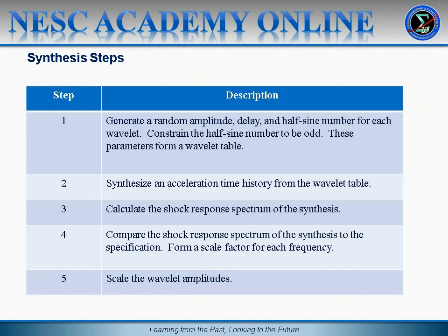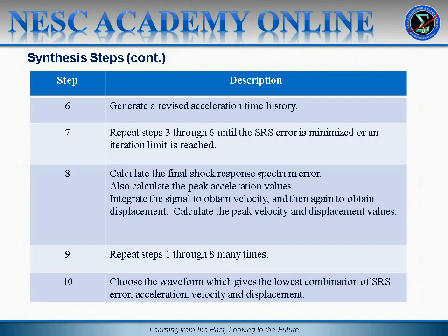Then we calculate the shock response spectrum of the synthesis for step number 3. Then for step number 4, compare the shock response spectrum of the synthesis to the specification. Then form a scale factor for each frequency based on the amplitude of the synthesized SRS and the amplitude of the SRS specification. We then scale the individual wavelet amplitudes in step 5.